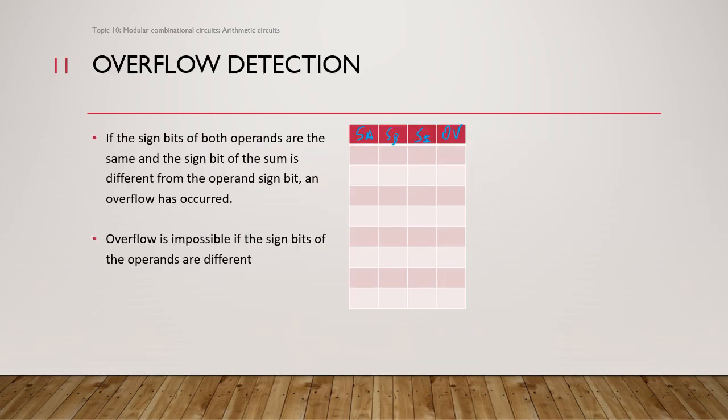And we can add more functions to our adder-subtractor circuit, like overflow detection. This is also important because we need a circuit to tell us the result is wrong, that it's overflowing. Actually, you can see this in your calculator sometimes, right? If you input some ridiculous number there, you could see overflow.